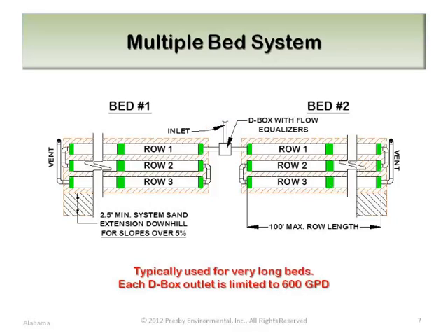Each bed of a multi-bed layout must have at least 50% of the required Presby pipe. More is allowed, but never less. In this example, each serial section is vented separately. However, they could have been joined together and taken to a single vent stack.